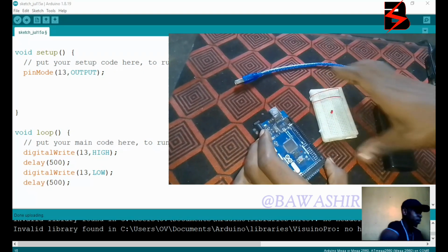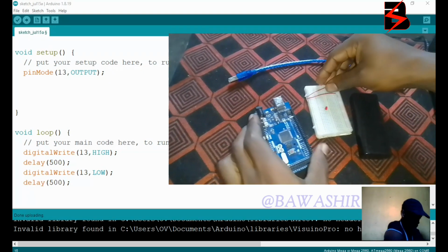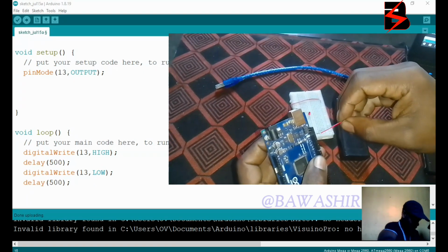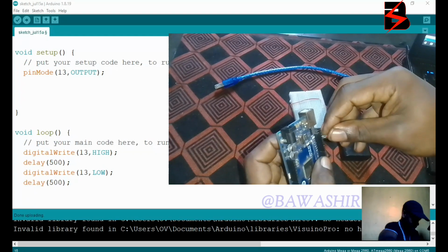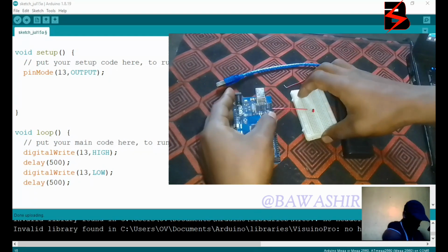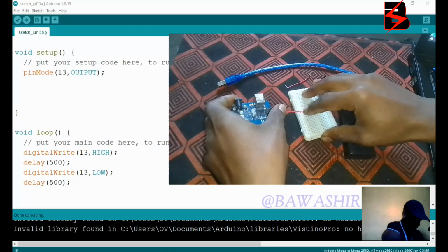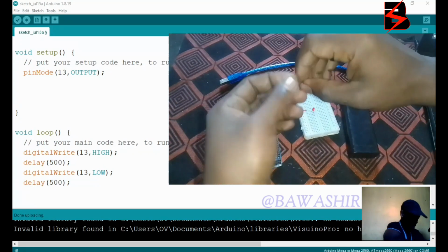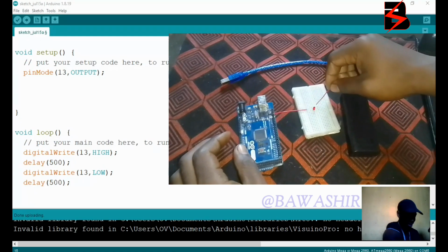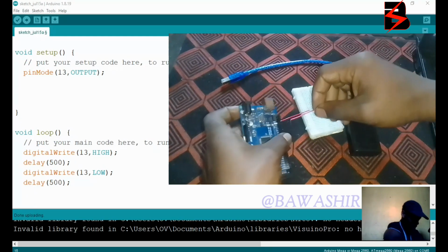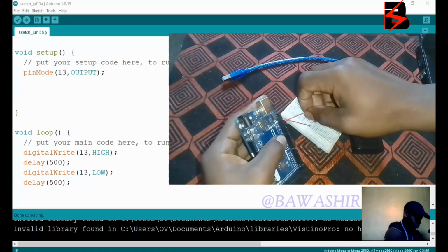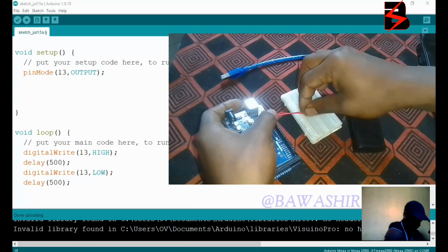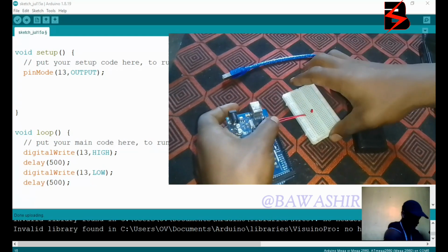So with the hard wiring, allow me, I'm going to use the ground pin. I connect it to the ground of the LED. Please, using a breadboard also needs some basics. Someone can ask, why am I connecting this way yet the LED this way? They are connected. That's breadboard knowledge. Then I'm going to put here in pin 13 and give the live to the LED, as you see.